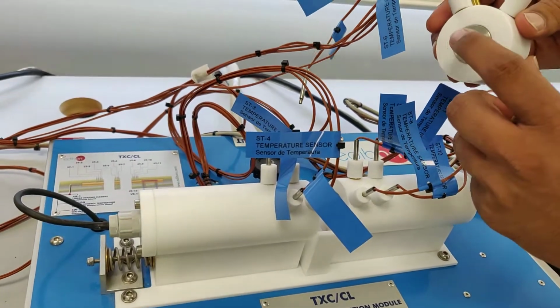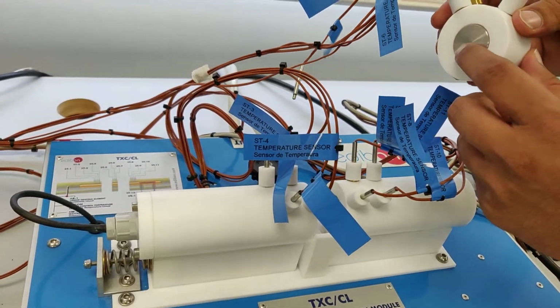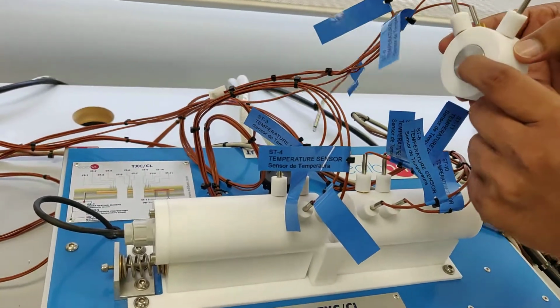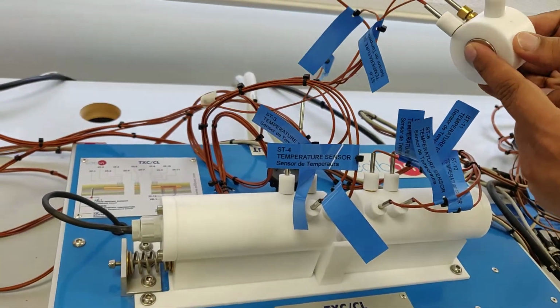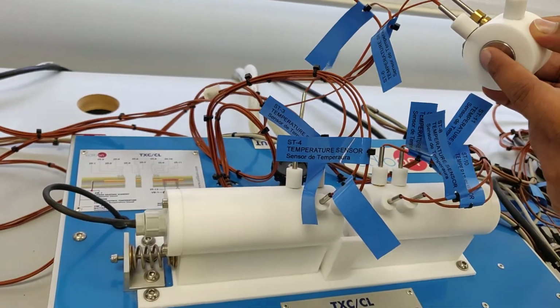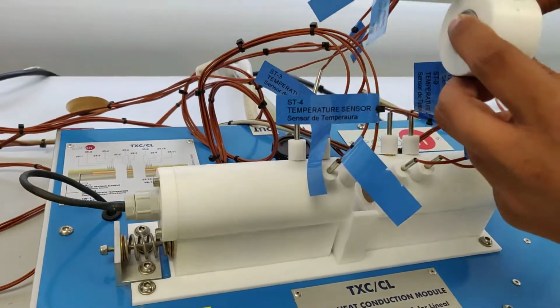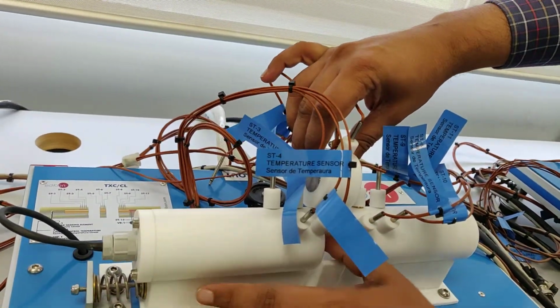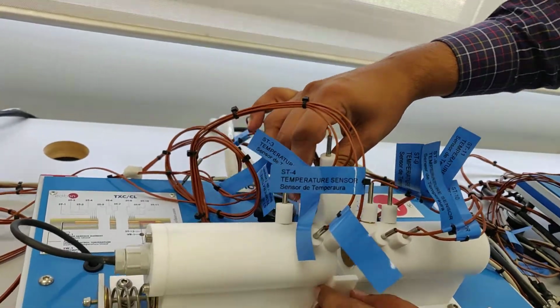So all we need from the machine, if we are trying to find the thermal conductivity of this material, we need delta T between the two sides, or for the length of the specimen. So T5 and T7, if we can record from the system, then I think with that we can do the calculation to find the K value. Now I'm going to put this back in here.